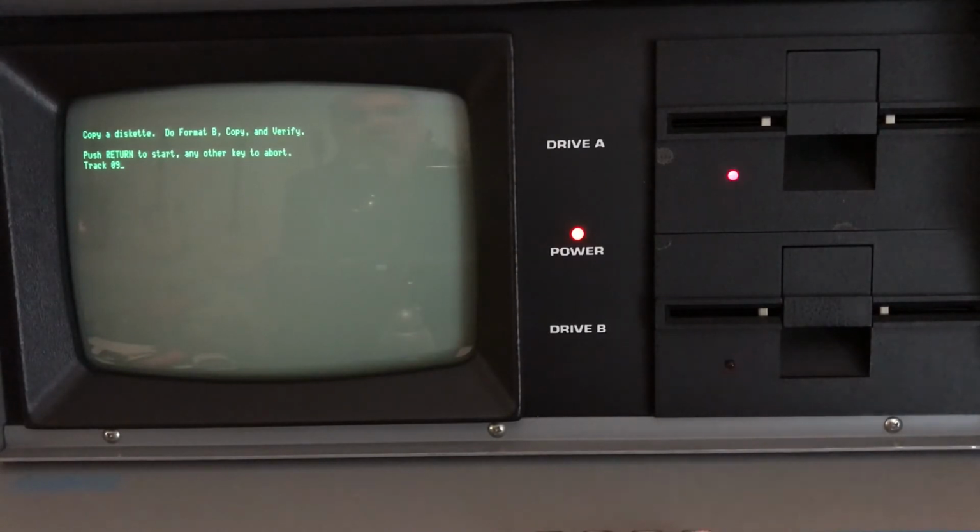I'm guessing that power supply could probably be recapped. You know, I'm seeing noise on the screen as the disk heads load and unload. It definitely reacts to the motor starting and stopping. The monitors typically use 12 volts to operate, so I'm sure it's sharing the same 12 volt rail the floppy drive motors are on.